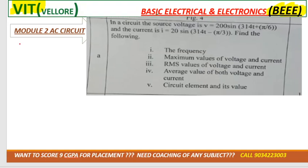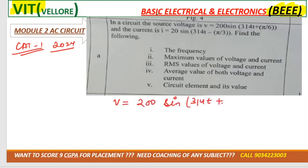So this is again your CAT1 exam paper, 2024. In this they have given V is equal to 200 sine (314t plus pi by 6), right? And I told you the standard equation: V is equal to Vmax sine omega t plus phi.